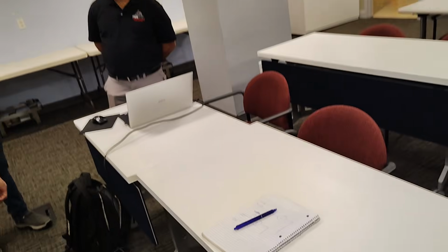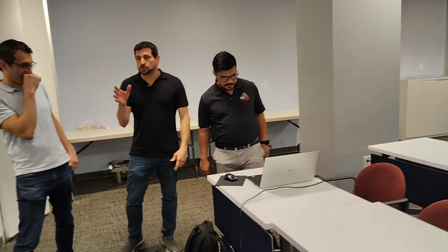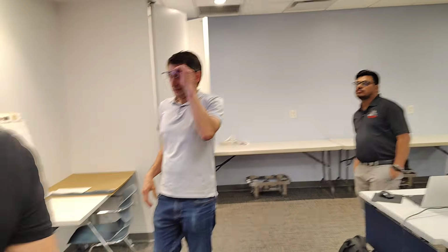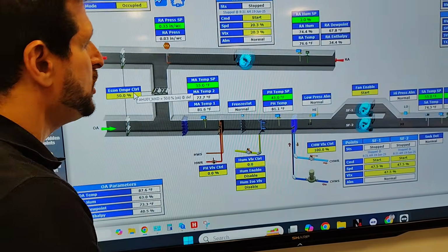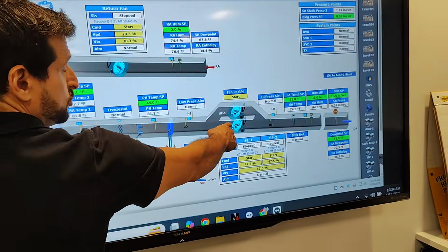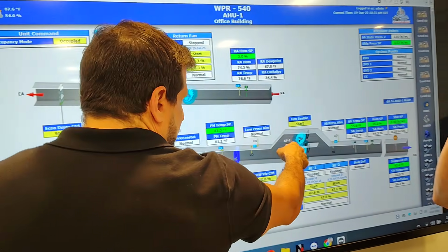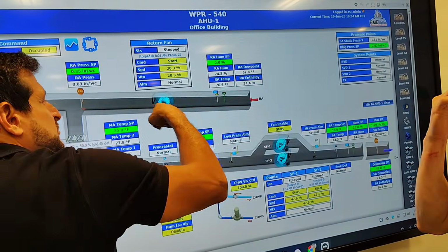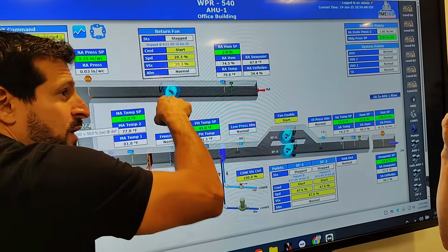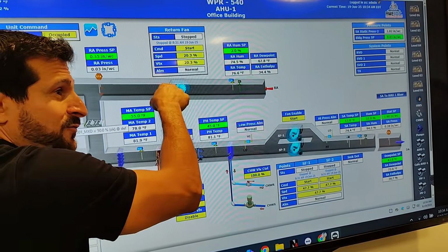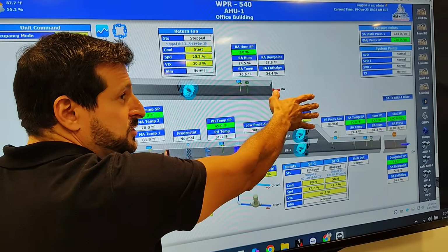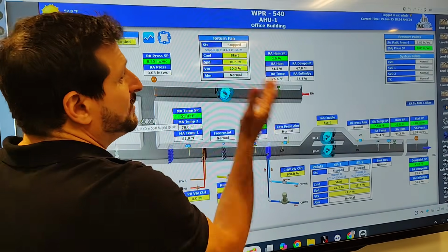No, that's cool. But so the dampers, it's a tricky thing, right? You don't just want to arbitrarily force those, because let's say you have a situation where you close this off, right? Now I'm going to say I don't want to spill anything. I don't want to bring in any outside air. I close this off. Well, if this fan is doing 2,000 CFM and this one's only doing 1,000 CFM, what happens now is the pressure of this fan is going to force this fan to go faster than the motor wants it to go, and now you've created a generator. And you have a problem where you're shooting electricity back into your system. So you can't just do whatever you want with these dampers.